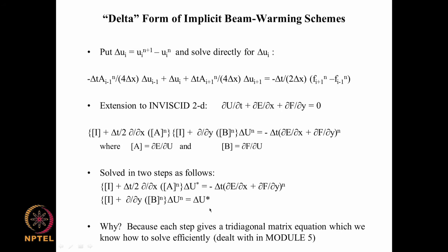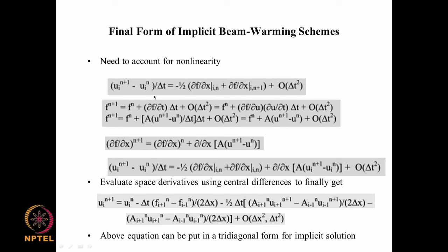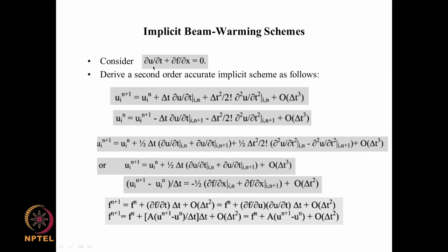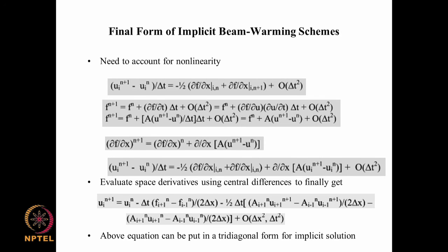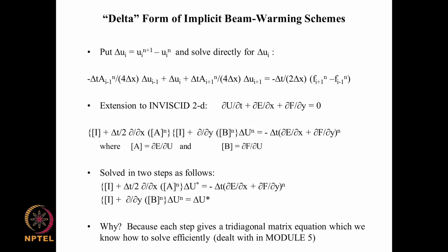Now, in this method, this looks a straightforward extension of the method that we have seen, and that is possible because what we considered to begin with is just an advection equation without any viscous terms, without any diffusion terms, but our Navier-Stokes equations do have viscous terms.